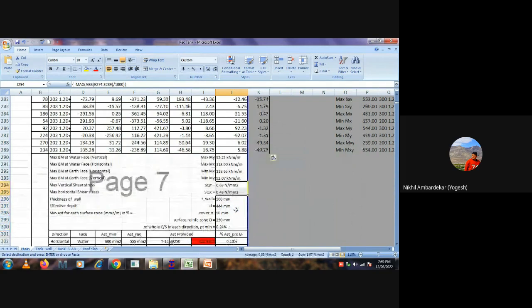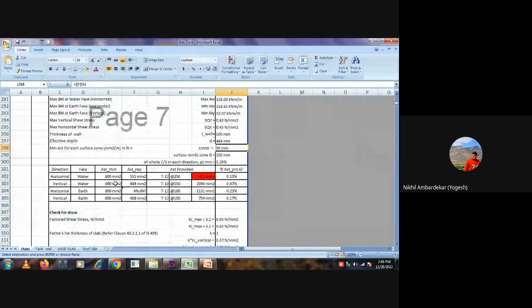What is our wall thickness? It is given already on the first page. It calculates the effective depth based on the bars; cover we assume 50. Okay, so now you have to adjust the reinforcement. Okay, so red means it is failing.